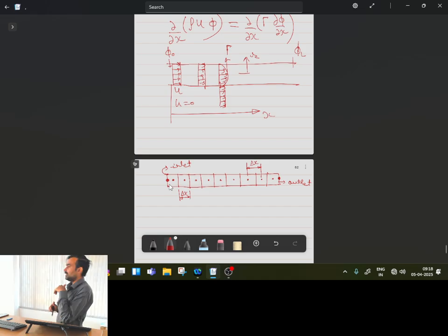So ultimately in the finite volume approach, we need to define some node point at the face center points in the particular direction along which the boundary is lying. Is this one clear? So I am having two more additional nodes at the boundaries, and typically the distance of the centroid node to this boundary node will be delta x by 2. All are clear with this point?